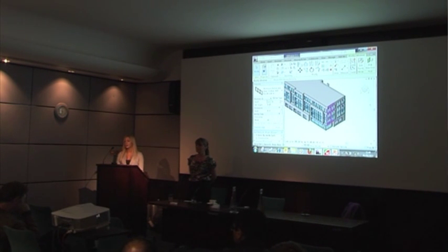A way that I look at it is that if I have a model that's, let's say, 10 rooms, and only one of the rooms is giving me a problem, I know in IES I can delete that room, redraw it, see if it works. If I get a model that's 10 rooms and 9 out of 10 rooms are a problem, it's probably going to be better if I start over. So it's all about the quality that you're starting with. So you can, I think, feel very free to go back to an architect and say, this is unusable for what I'm doing. And also provide them documentation on why.